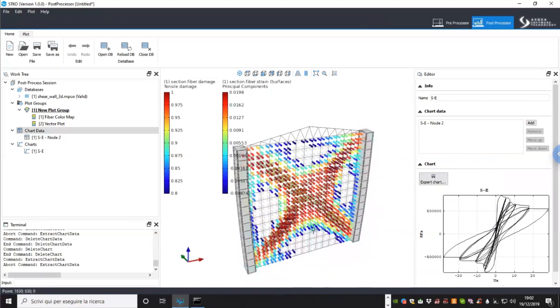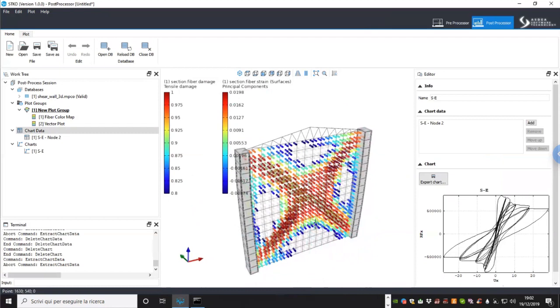But of course, for multiprocessing, we didn't include the OpenSees MP inside the installation. You need to compile it by yourself. So in the STKO installation, you only have the sequential OpenSees. But if you have your own version of OpenSees compiled for parallel processing, or if you want to use the one on DesignSafe, you can do it.